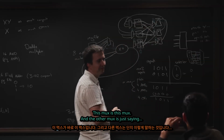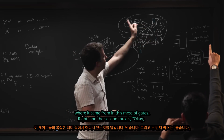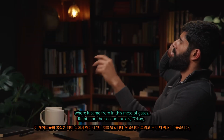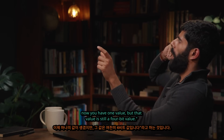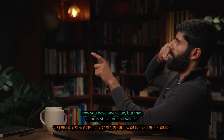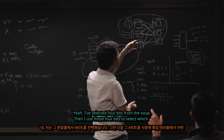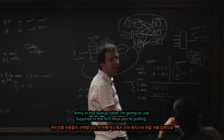Got it, okay. And then the other mux is just saying where it came from in this sort of mess of gates. Right. And then the second mux is, okay, now you have one value, but that value is still a 4-bit value. Yeah, so I've selected 4 bits from the soup. Right. And then I use those 4 bits to select which entry in the lookup table I'm going to use.